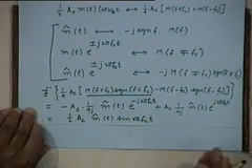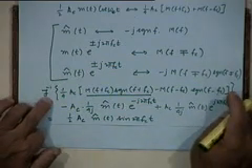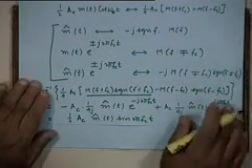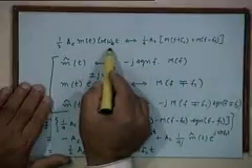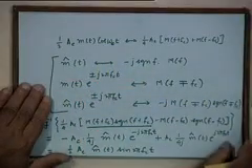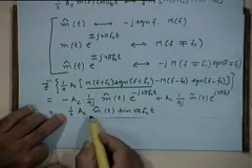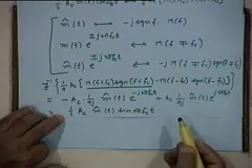So I have a closed form expression for the inverse Fourier transform of the last two terms. The first two terms were equal to half AC mt cosine omega ct, and the last two terms are equal to half AC m hat t sine 2 pi f ct. Very interesting.